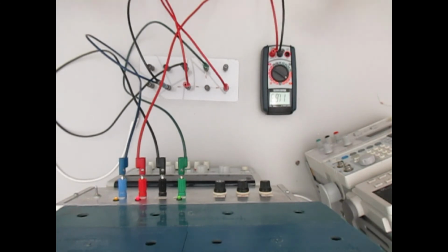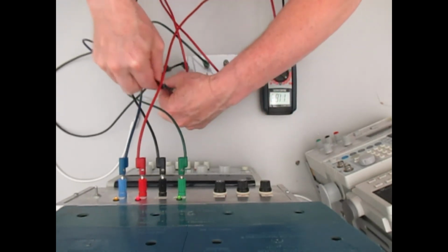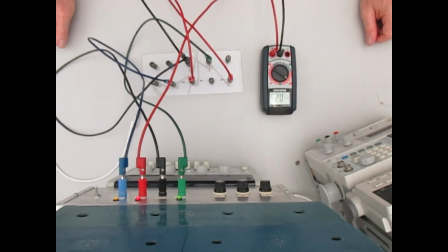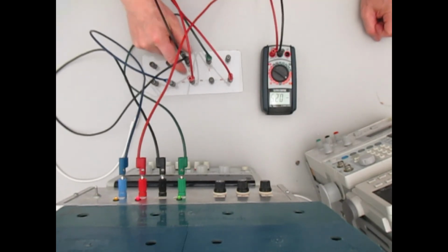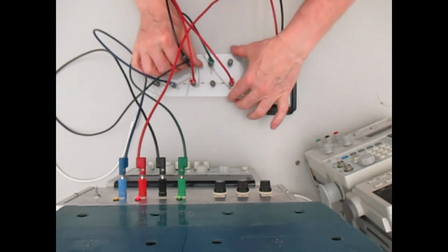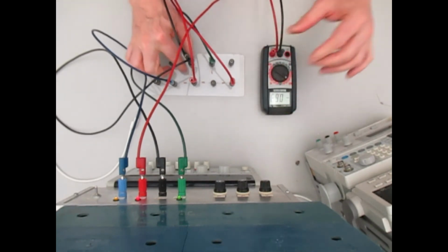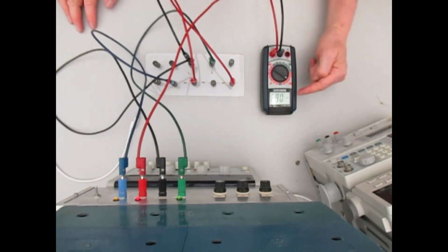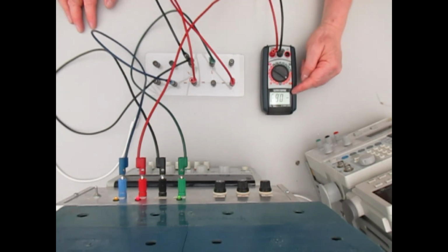Okay, but now what we want to do is measure E Thevenin and R Thevenin. So what we need to do is put the voltmeter across the R4, or in this case now it's the R load. We disconnect the bottom of this, so basically we're removing the R load resistance, and right now we are measuring the E Thevenin. So E Thevenin is negative 0.63 volts.